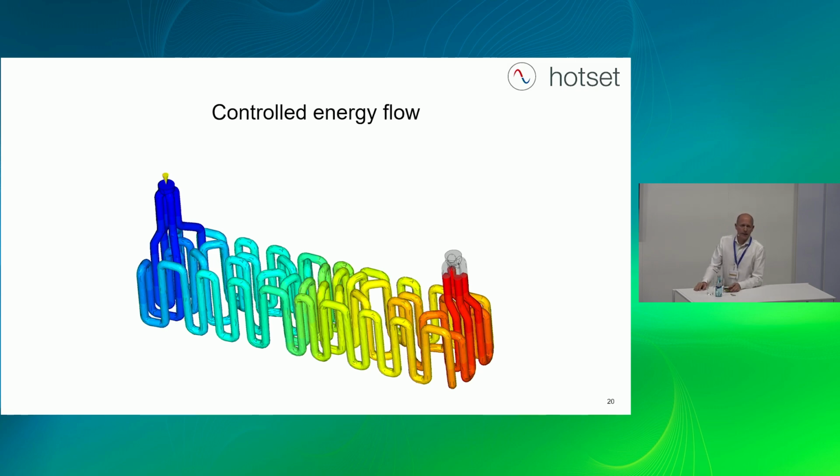And he did it. One week later, I got a call from him, and he said, it works perfectly, even better. I can reduce my cycle time. And I said, now you have two options. You run this insert in this way and receive a better cycle time than your process before, or you use this technology in all of your molds and increase the temperature of your water, which means if you increase the water temperature of your cooling plant, you save a lot of energy cost because maybe you don't need the compressor power consumption.